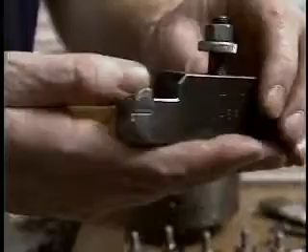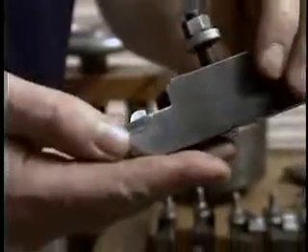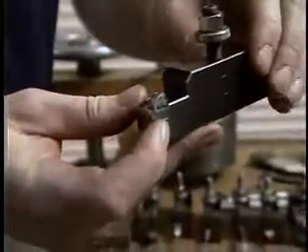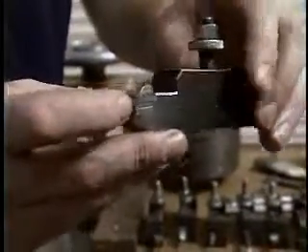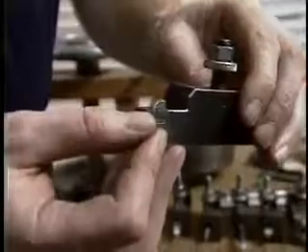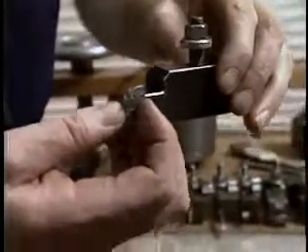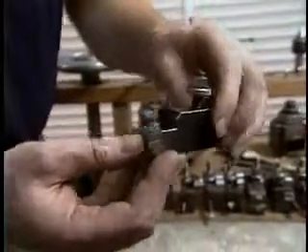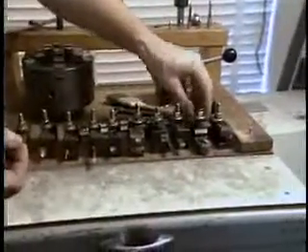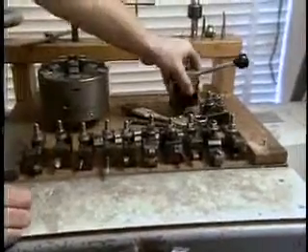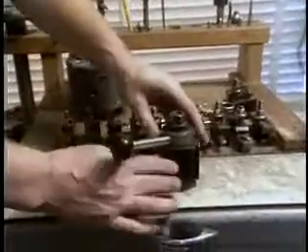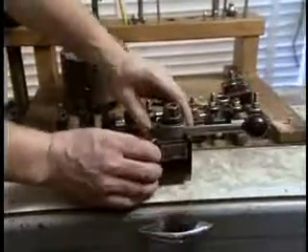This tool holder is used to hold tungsten carbide inserts. These triangular inserts can be used when the end gets dull: remove them, rotate them, and you have another fresh tool to work with. All of these tools are held in this tool holder.